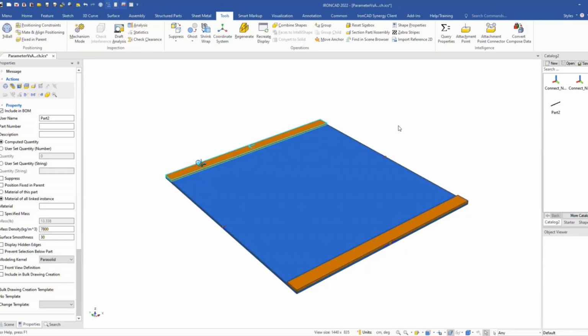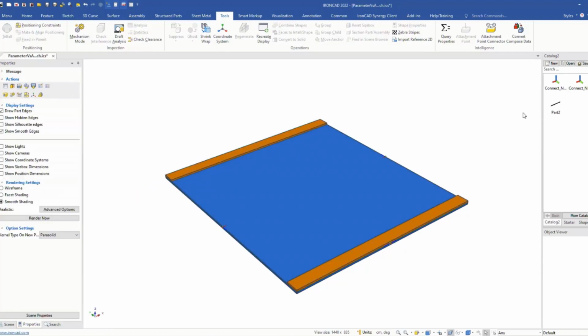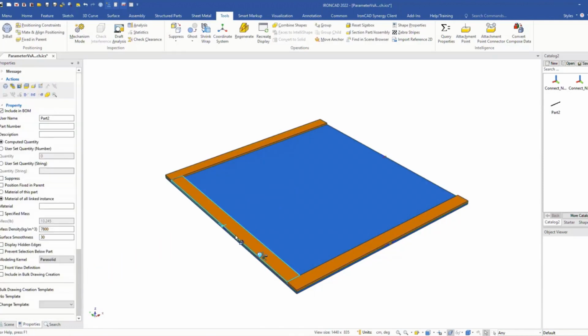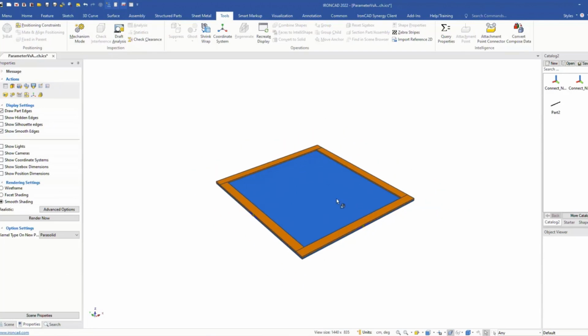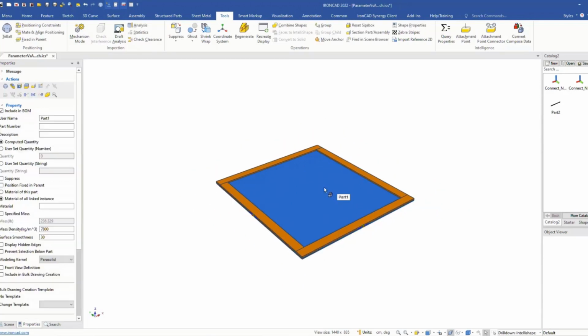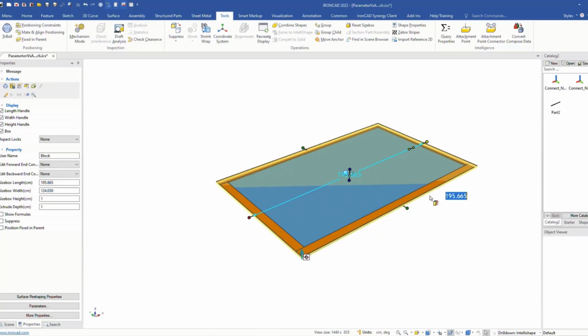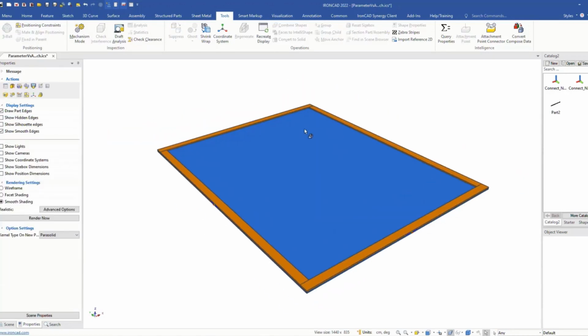So I can drag and drop this onto the other side. You notice it does the same thing. I can drag and drop it here. You notice it took the 14 off, snapped it to the center, and automatically applied that. So it built all that intelligence as we were dropping. It still has the same behavior. If I adjust this, notice everything will update because it built it as an expression to do that, so we can do it either way.